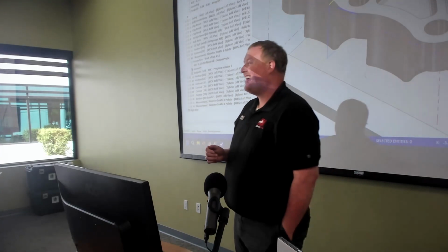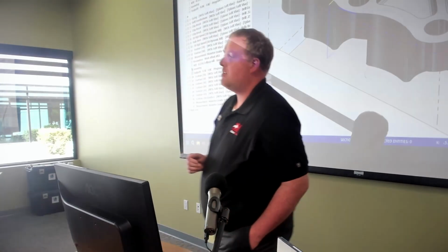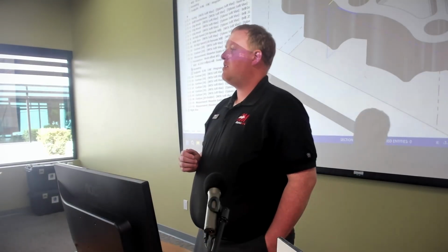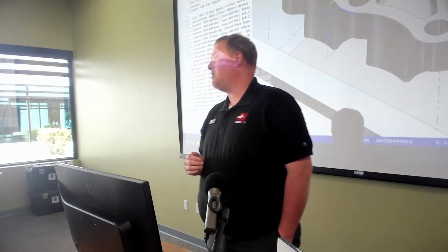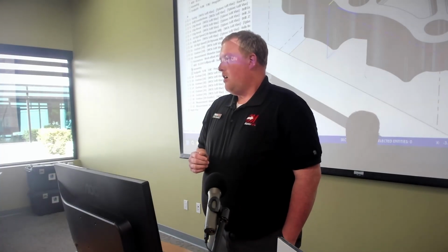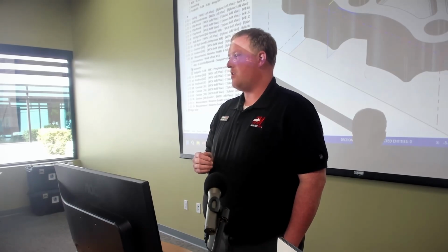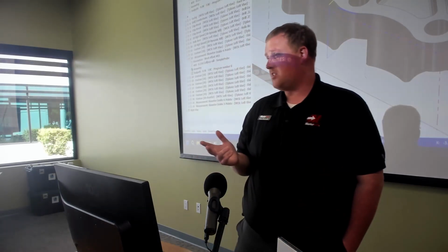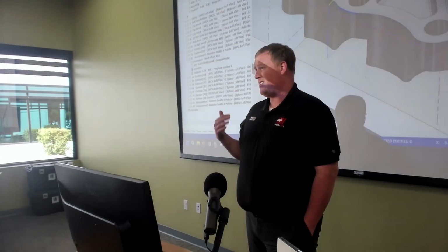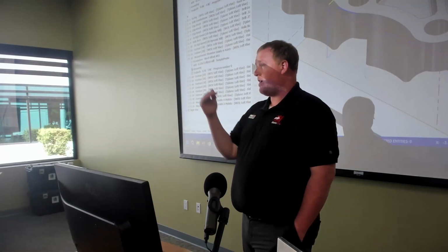On the tool detection, if the tool broke, sometimes they're so sensitive that when they're dull, the whole machine actually stops, like thinking the tool broke, but it's actually just dull. Does that happen a lot with this system? With the probing? We'd have to talk about it and see how you're programming it, because there are different inputs that tell it tolerances for either breakage or pull out. So what's the threshold?